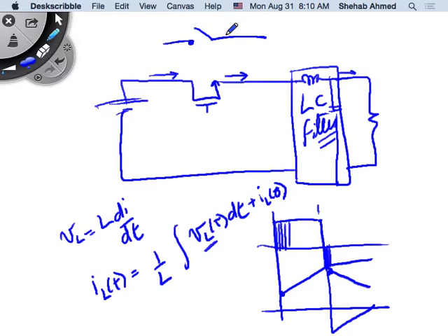Maybe if you were in the contracting or construction business, you probably saw many contactors put in different places when you want to create a startup circuit for an air conditioning system, or you want to turn on loads and turn off loads in sequence in a certain fashion, and you will do that using contactors. So your PLC, your programmable logic controller, will probably send outputs to contactor contacts to turn on and turn off, etc. So these are turning on and turning off power contacts. At low voltages and current, it's no problem. But in a power system, you saw what happened, right? But why is that happening?